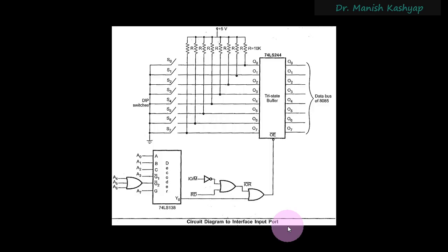But before that, let me also tell you, when the microprocessor is trying to deal with an input output device in input output mapped input output mode, in that case, your address bus is of 16 bits and the data bus is the lower byte of that 16-bit address bus. So from AD0 to AD7, you will have the port number which is there for addressing the particular input output device, because you can have at max 256 input output devices. So the content on AD0 to AD7 will be exactly the same as the content on AD8 to AD15.